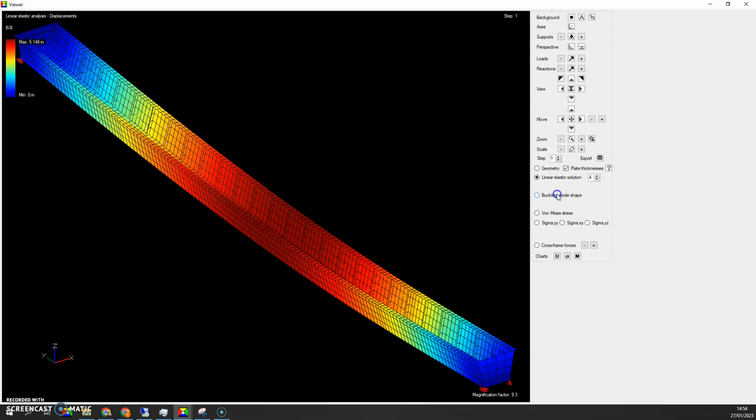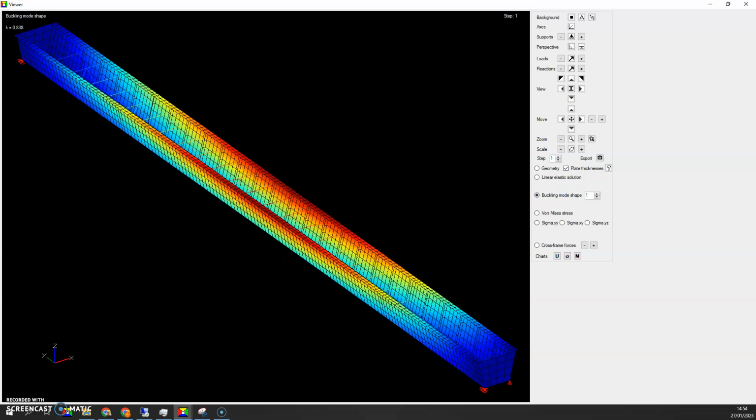Now let's go to the buckled shape, and as expected, we've got an eigenvalue that's less than 1. And that's even considering a bridge that's perfectly straight, with no initial imperfections. So it is actually unlikely that we would get to this point in reality. Something less than 1 is pretty bad, so we really want to stiffen this bridge. Unfortunately, this is an actual bridge that collapsed and killed 3 people on the site. So we will still try to see how we would do this differently today.